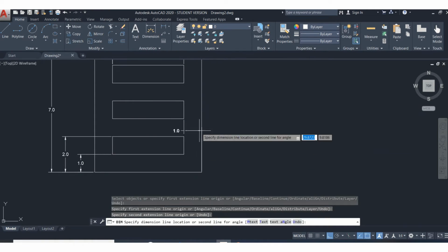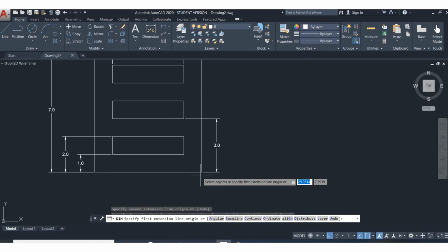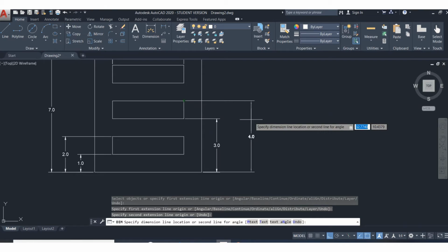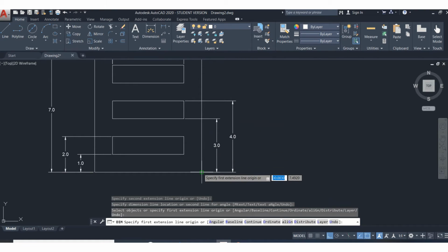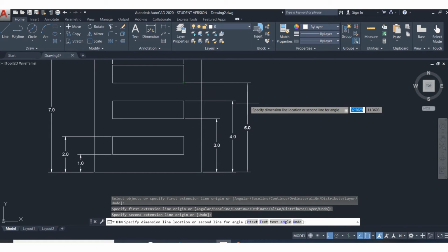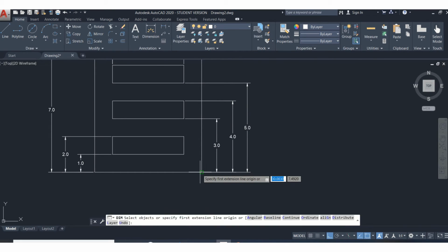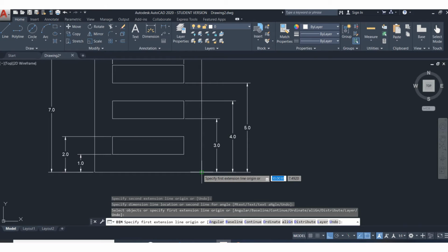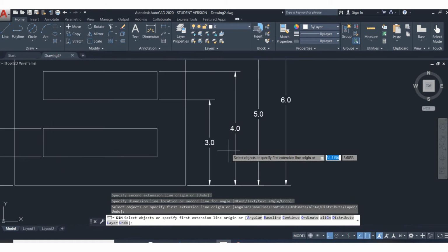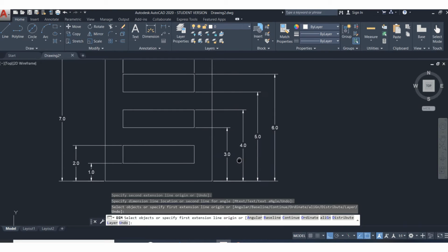Let's see here. Remember, don't crowd your part, but also at the same time, don't have to get crazy and put it super far away. And notice what I'm doing is shortest dimension, and then the next longest dimension, and the next longest, and so forth. Simple, easy, straightforward way to dimension. Also, way to interpret it.